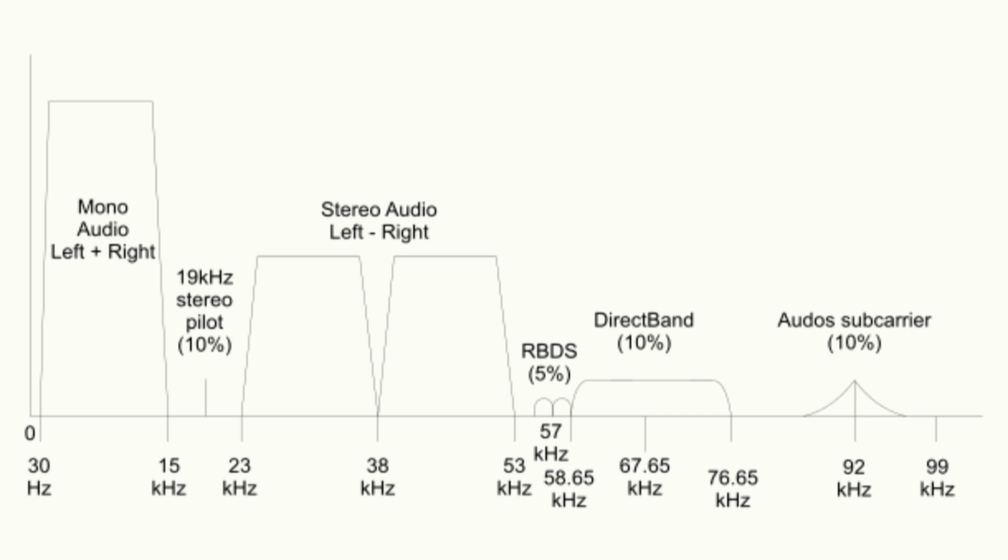Anybody who's bought one of those cheap FM transmitters to play with their MP3 player or CD player in the past will have experienced the noise of the pilot carrier, or pilot tone, beating with the audio on cheap CD players that had crappy filtering. Some of the earliest Discmans actually had very little filtering at all, because they figured, okay, the subsampling frequency is going to be around 22 kilohertz, so you're not going to hear that anyway, so why bother to filter it out?